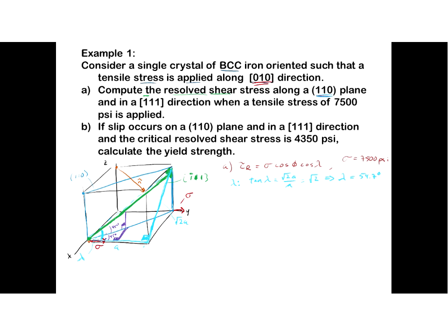Yeah? So instead of there, let's draw it right from that same origin point, and we'll draw it pointing out here. The angle right here between stress and the normal to the plane is 45 degrees. Let me actually say that that's 45 degrees. This is phi, which equals 45 degrees. You don't even have to calculate it. You can just look at it from geometry here. All right, so great. So phi is 45 degrees.